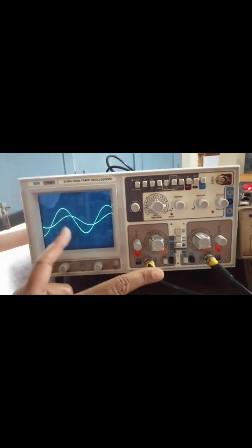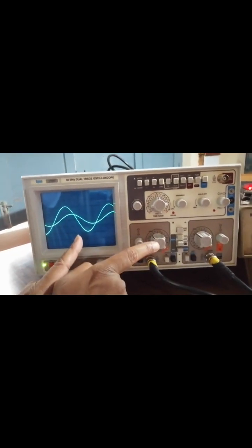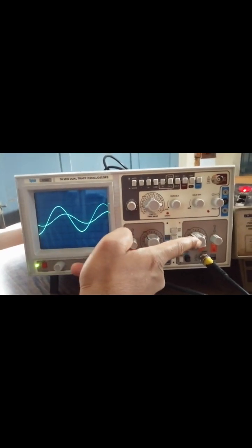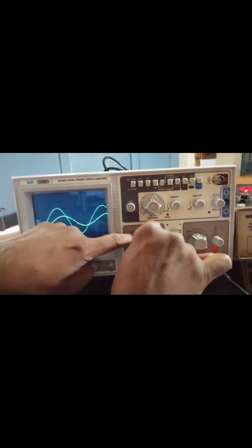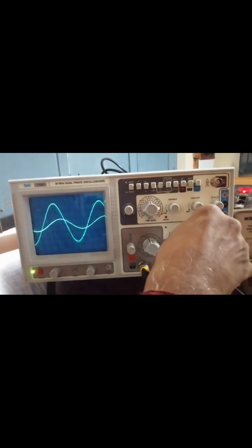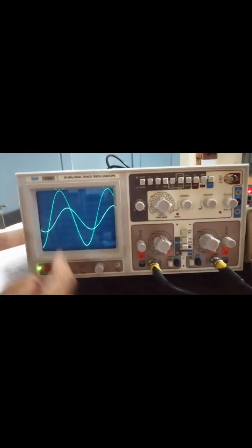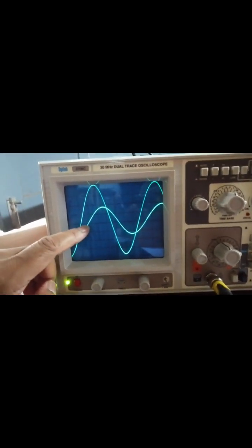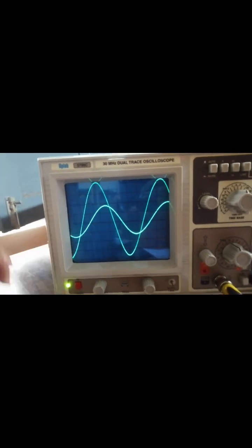But keep this point in your mind: if you change the multiplication factor of the input channel, at the same time you change the multiplication factor of the output channel also. Say if you move from 1 to 2, here also you should move from 1 to 2. So now these curves become more and more steeper, and you can perfectly read whether it is passing through 0.8 or 1, something like that.